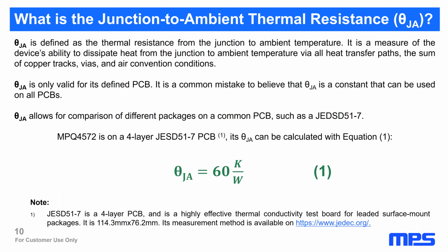It is a common mistake to believe that theta is a constant that can be used on all PCBs. That sentence you have to keep very well in mind. Theta is only valid on the PCB where it has been measured. Theta junction ambient allows for a comparison of different packages on a common PCB, mostly measured on the JESD51-7. You can find this PCB as an image on the JEDEC.org website.